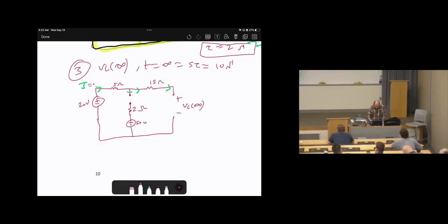So I equals 0. There is no current here, even here. I equals 0. Here I equals 0. There is no currents because, again, there is no possibility to make any closed path. No closed path for the current to flow. So as a result, what do you think the voltages of the resistors will be? Zeros. So here V equals I times R, which is 0. All of the voltages are zeros.